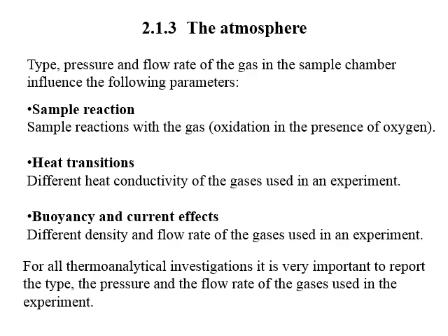The atmosphere is actually important in TGA analysis. The sample reaction will depend on the gases that are present in the reaction. The most common atmospheres in TGA are generally either air or nitrogen, but people can do it with argon, people can do it with CO2, but understanding the reaction that may or may not occur depending on the gas that you choose is important to understand.